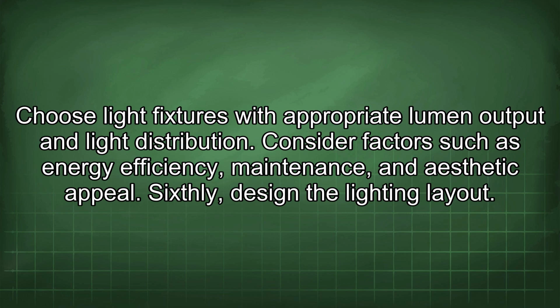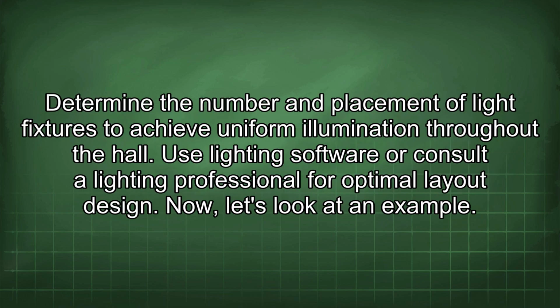Sixthly, design the lighting layout. Determine the number and placement of light fixtures to achieve uniform illumination throughout the hall. Use lighting software or consult a lighting professional for optimal layout design.